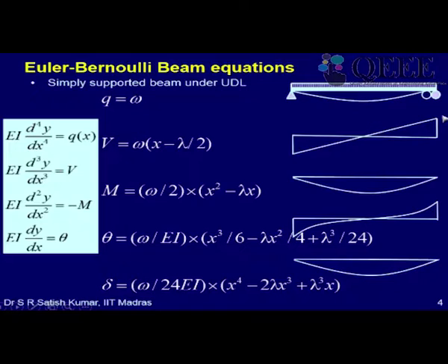So there is a discontinuity in the shear force diagram, and consequently there may also be a slope discontinuity in the bending moment diagram. So a bending moment diagram will look like an inverted triangle. There will be one slope here and suddenly the slope will change and there will be another slope here. Okay, so that is how it will come. But with reference to the slope and the deflection, there will be no discontinuity. So slopes and deflections are continuous, only their differentials are discontinuous.